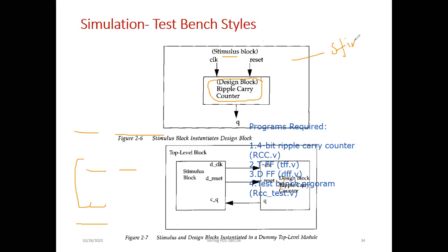What is the meaning of stimulus block? Stimulus means insert. Insert the values with the delays after the initial begin. That only is called a stimulus block. Here, in the stimulus block, we force from externally the clock value and the reset value. Based on that, I'll get the Q.